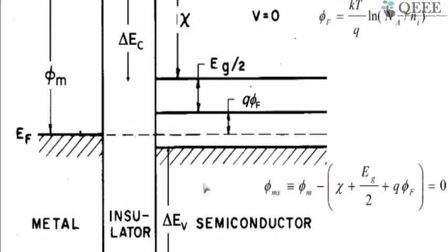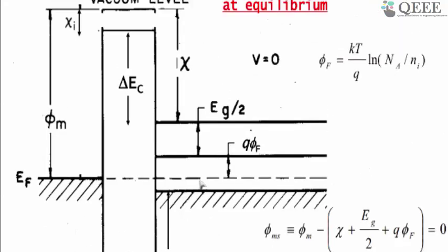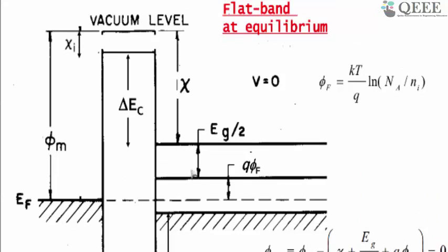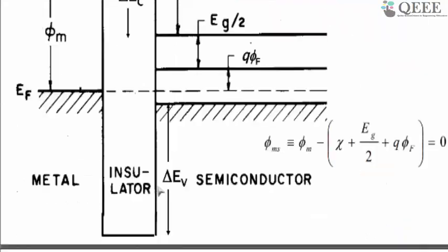This need not be the realistic case. For example, if you know the doping concentration, you need to choose the appropriate metal which has a matched work function. But in a real case, in a chip, we may dope the semiconductor differently in different regions. You cannot keep changing the metal from one place to another. Normally you may have only one single metal, maybe for interconnects or contacts. Then the doping concentrations could be different at different places.